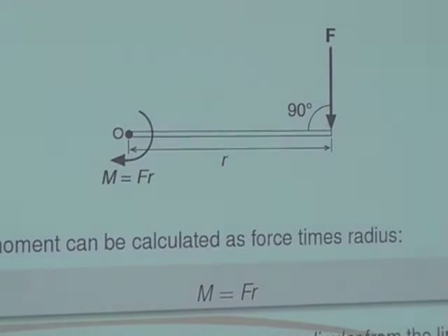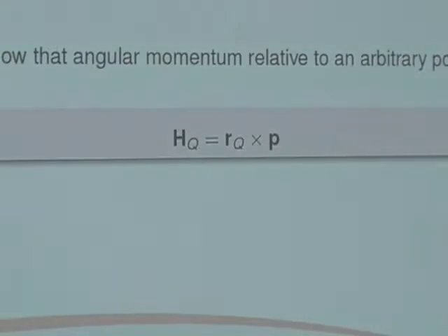So that angle there, which I've got on the diagram, is always going to be 90 degrees, okay? If the force is being applied up here to a pivot arm, but that force is in line with this one, then it's the perpendicular distance, not the direct distance, okay? That's moment. You've all covered that before. You should have done it last semester in stress.